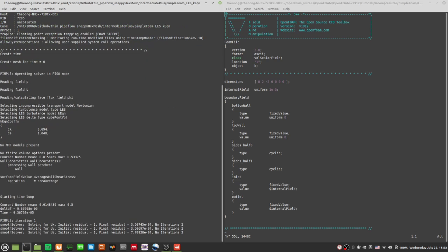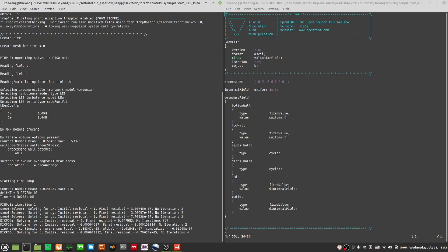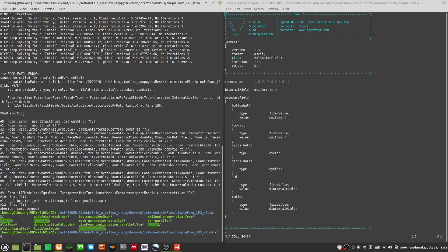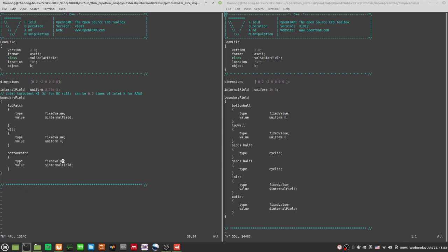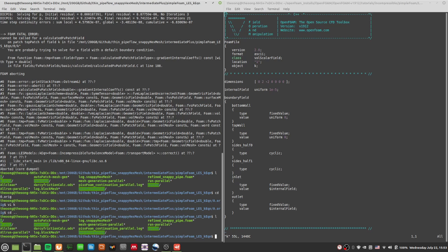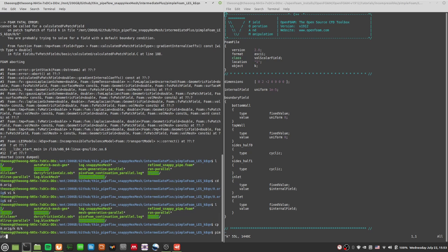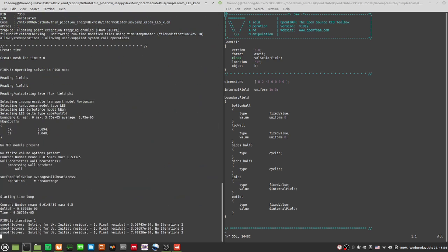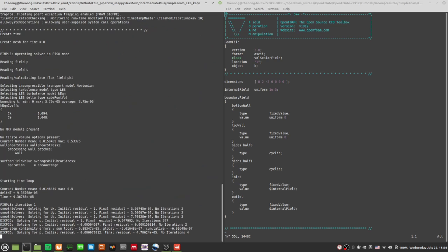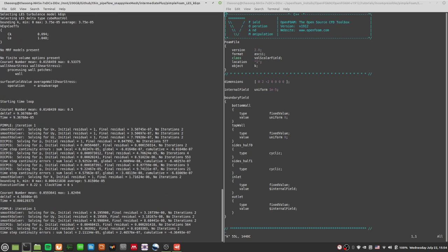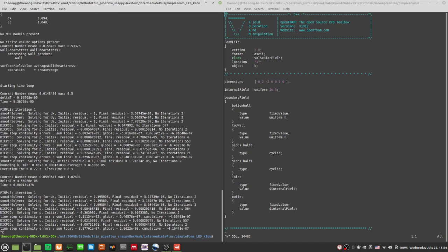So if I run pimpleFoam, it should be able to run nicely now for the next time steps. Again, it looks like there's still a problem, because I think I changed the files in the 0.orig. So I need to copy 0.orig/k into 0/k. Then I run pimpleFoam. This time it shouldn't crash. I forgot to copy the files over just now, that's why. So see, now the simulation's working. That's how you do your K equation, and that's how you do your Smagorinsky.